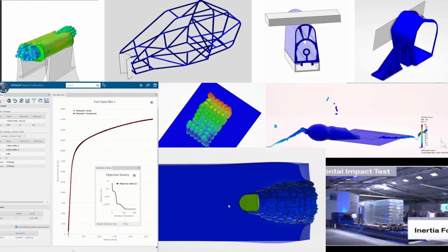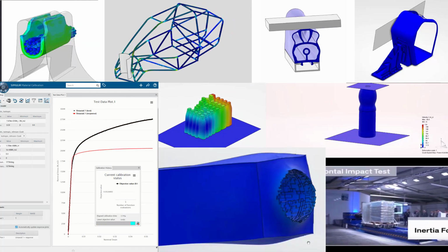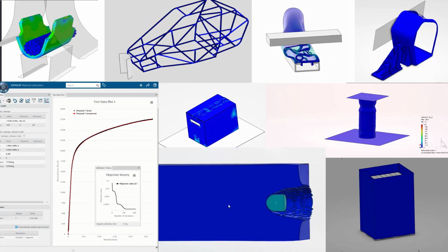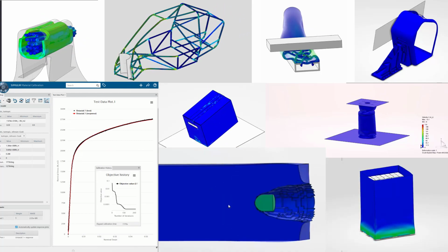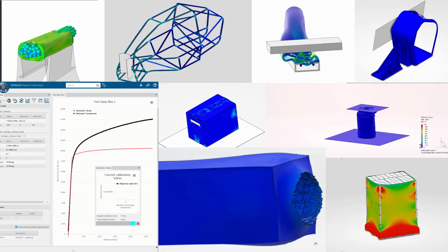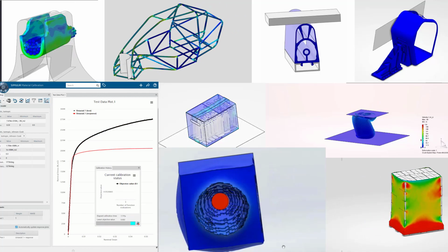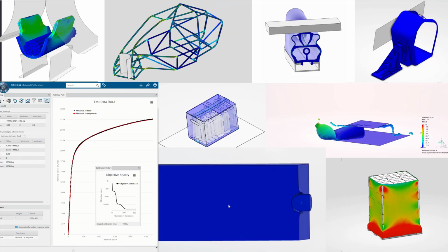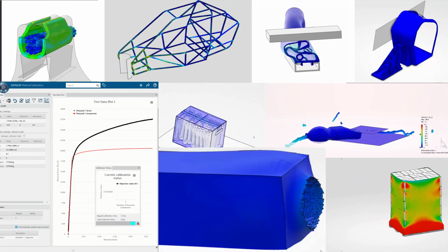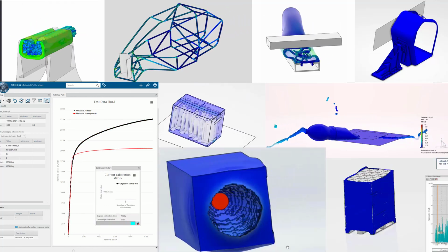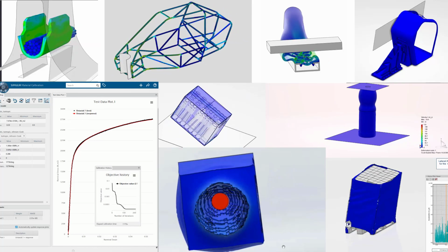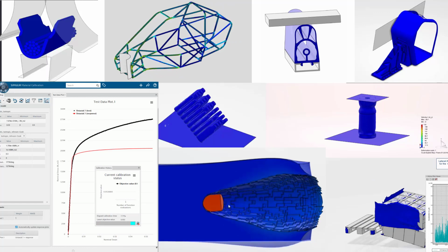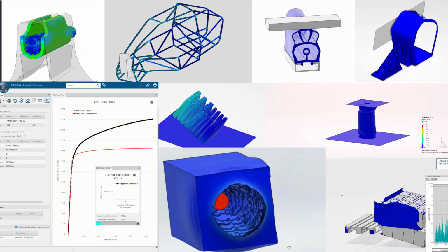stationary object. The next over on the top is a rubber gasket for a window, or let's say a refrigerator. What we're seeing here is a couple things. We're seeing an incredibly high strain application. So that is where a hex element comes into play. That's something that you just cannot do with a tetrahedral element inside a SOLIDWORKS Simulation Premium. That high strain application and the nonlinearity of the material is allowing for that crush to occur.